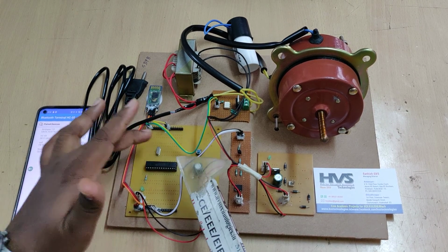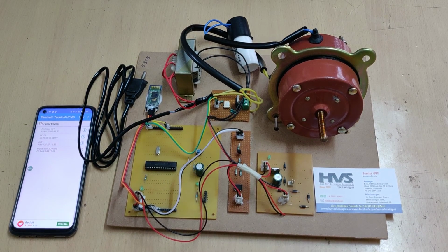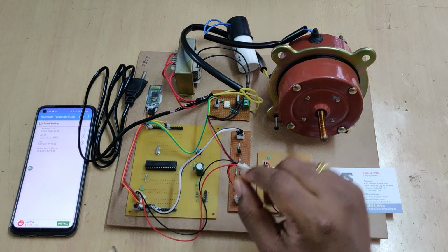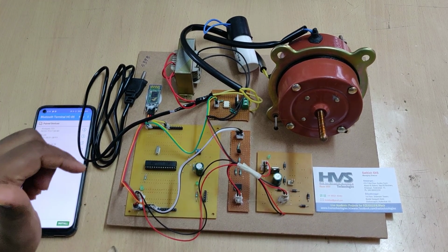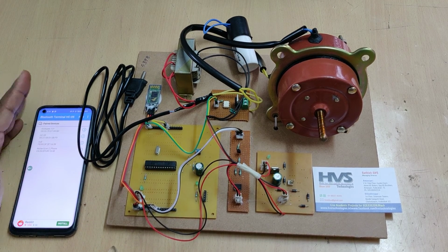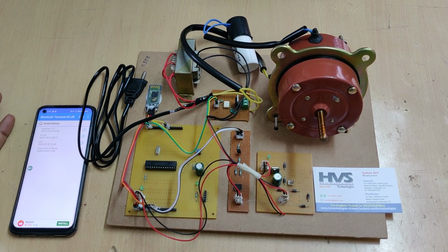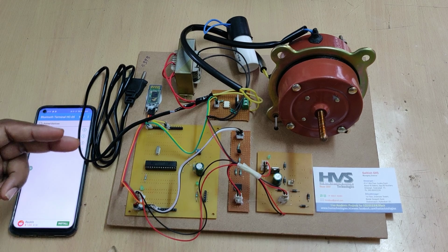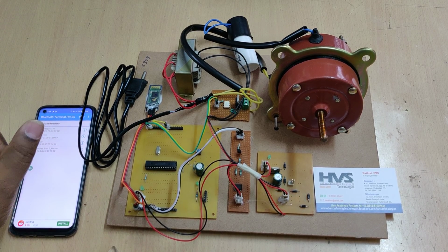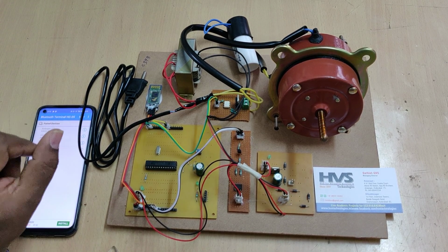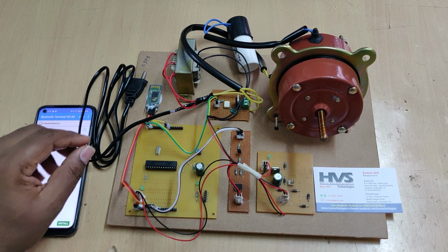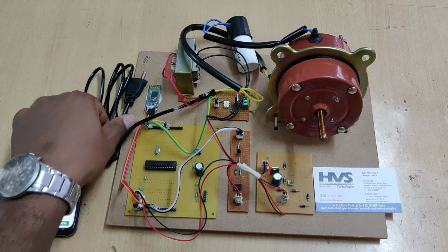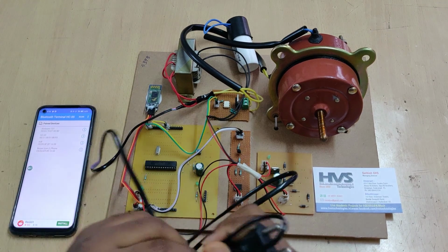We have provided the set of instructions to the controller to read the input signal and control the output triac. These instructions are coded inside the microcontroller in embedded C language. To control the inputs and outputs, we need to provide clock signals, one clock pulse per instruction. The controller is provided with 20 megahertz of oscillating frequency, so the controller can execute 20 mega instructions per second.